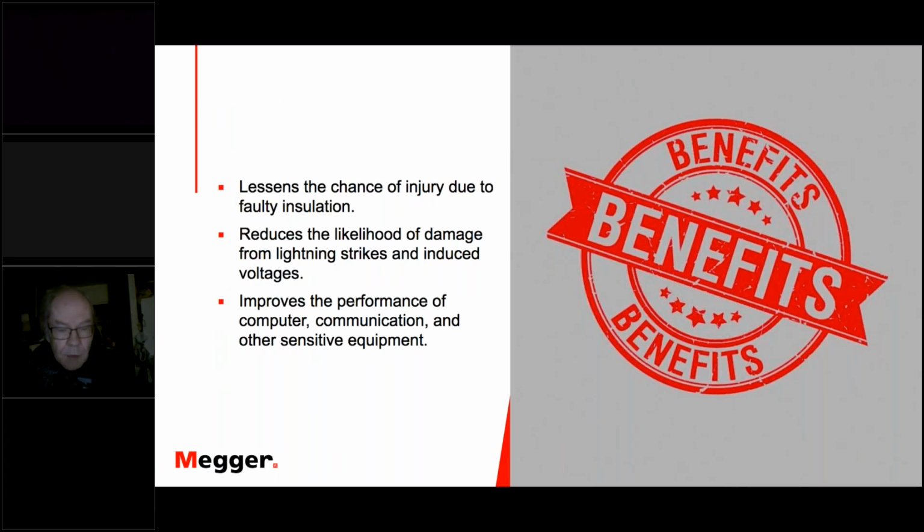So this is pretty much what I just led into. The main thing is you don't want voltage gradients developing from equipment to ground, because something has opened up in the electrical system and you no longer have a path to ground, and now you can develop a voltage gradient, and a person touches the piece of equipment at the wrong time and is injured or killed. You read this once in a while in the news from things like vending machines. That's an area where unfortunately that sometimes does occur.